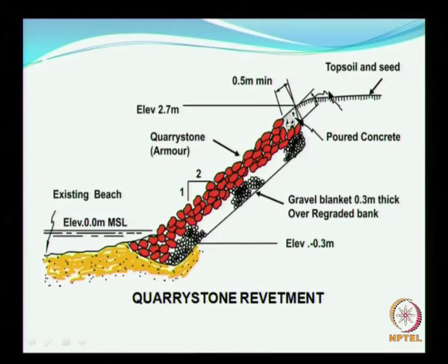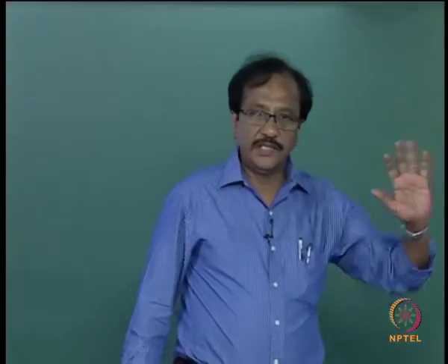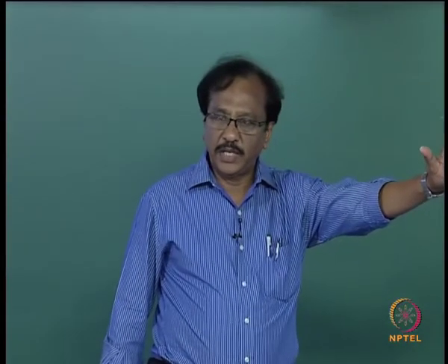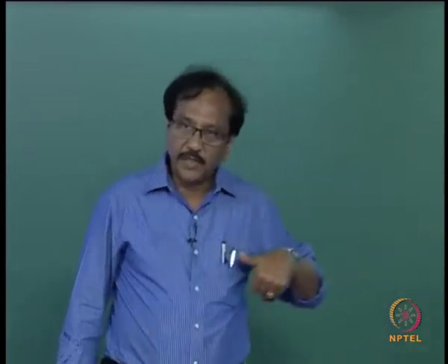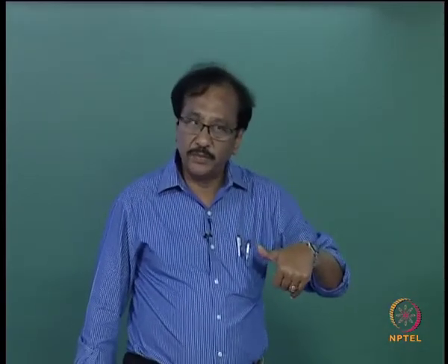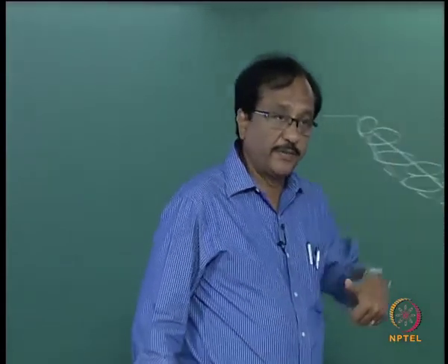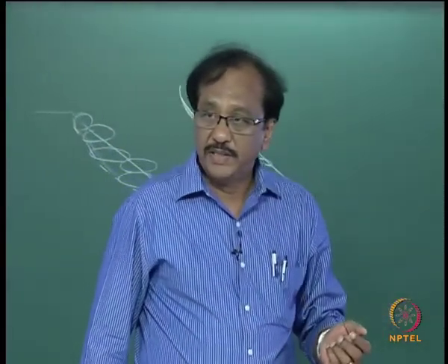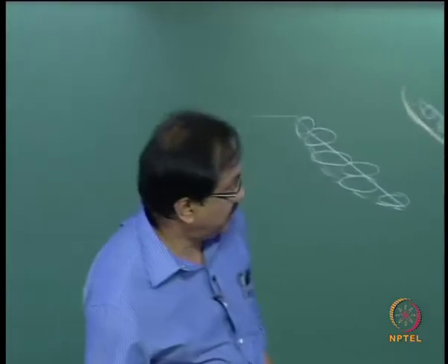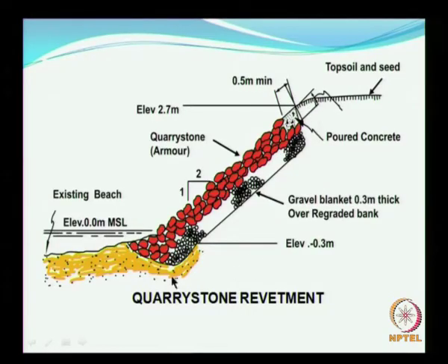During the tsunami there was a severe ingress of the water, and then the down rush back to the ocean comes back with tremendous speed. So the percolation of this tsunami water resulted in failure of the revetments as well as the sea walls, mostly sea walls.